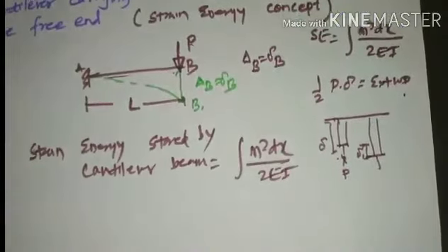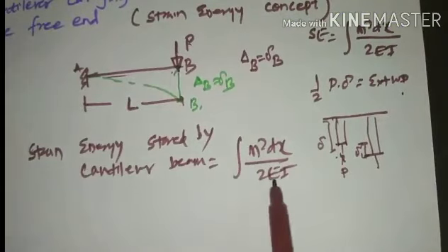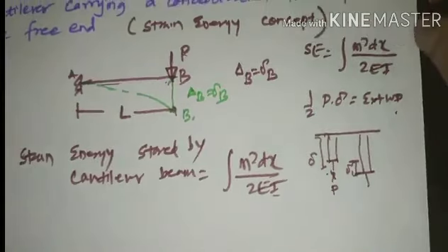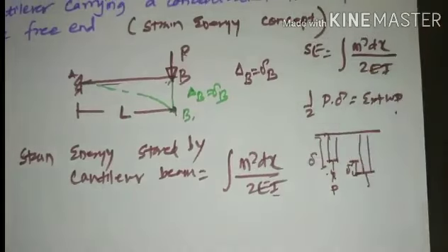Now, in each and every term we need to find the parameters that are required. E and I are constant, so we are not going to find any value related to them unless the values of E and I have been mentioned. If they are constant or uniform, or not mentioned, that means we shall keep them as they are. Now coming to the term M, M is nothing but the moment that we need to calculate.